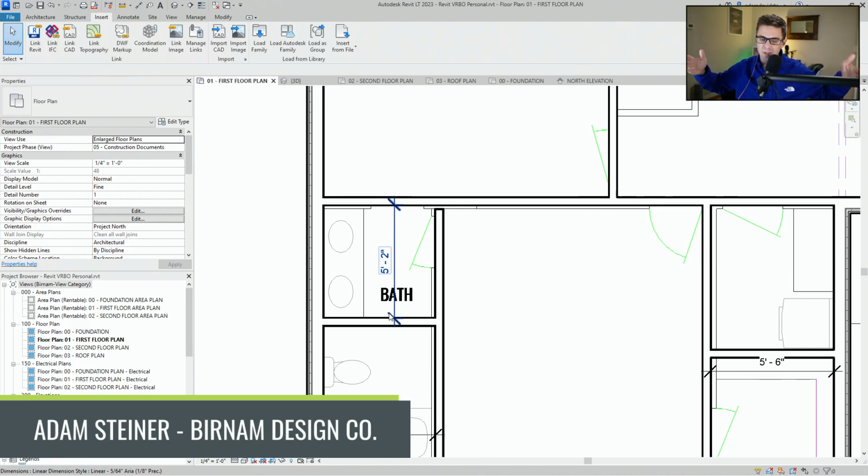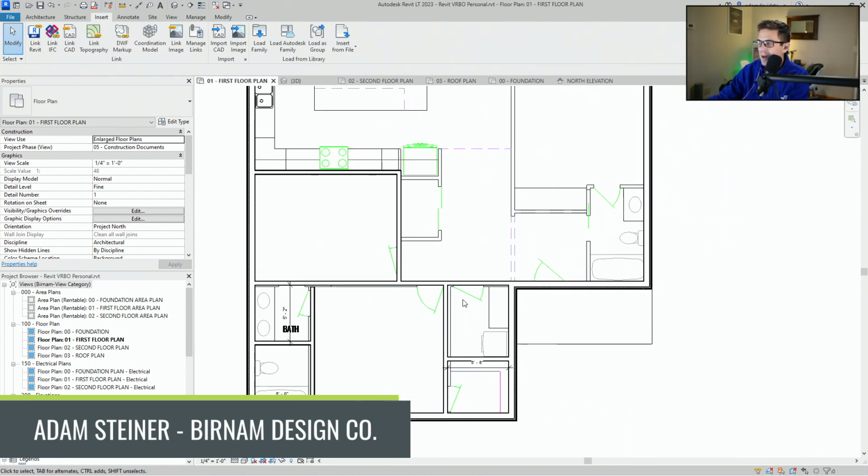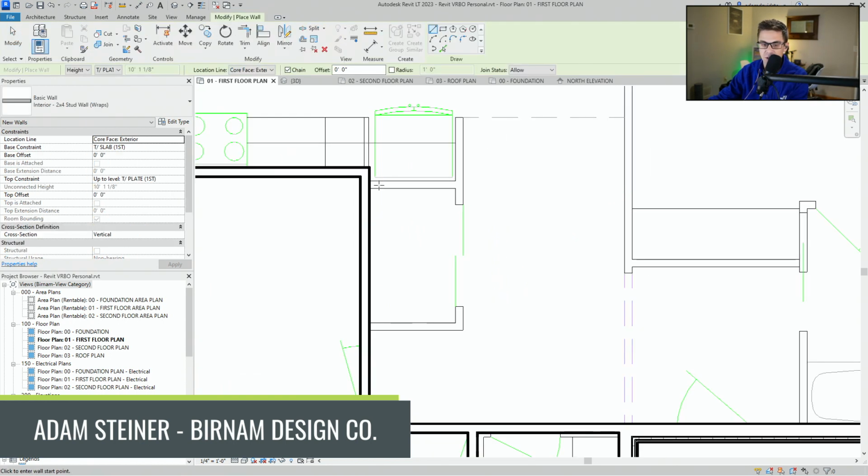The vanity tops are usually like stone or cultured marble, and they're easier to get in slabs that have just that little bit extra, so they can just plop them in there and don't need to cut. And then it being a little bit big also always gives you some wiggle room, because you know you can buy a 60-inch vanity. You know you can buy a 60-inch top. But if you buy that and it gets framed at 59 3/4 inches, you're screwed. So it gives you a little wiggle room with the drywall and all that. That's why I'm showing that at 62.